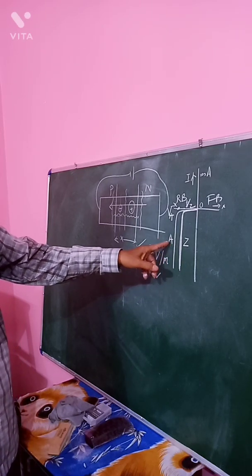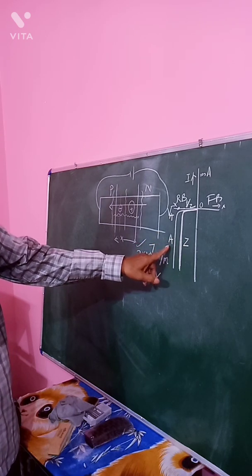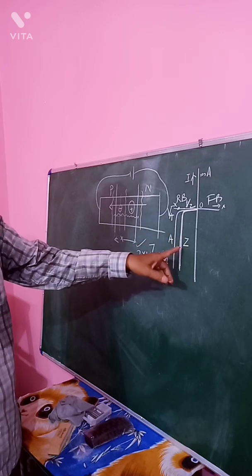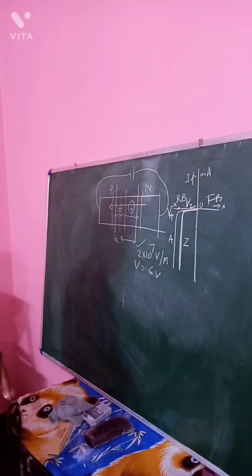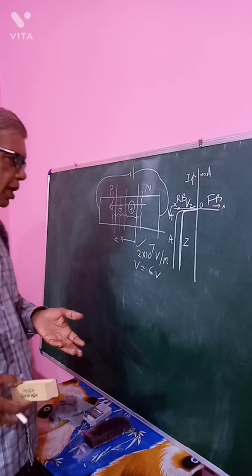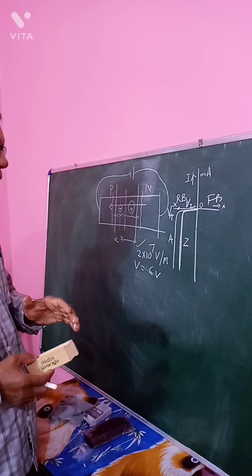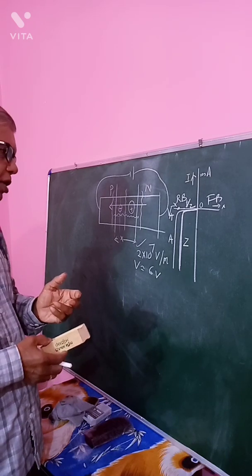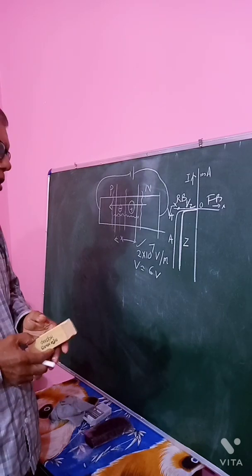Now, avalanche takes place because of collisions of electrons, Zener because of the rupture of covalent bonds due to high or intense electric field across the junction. Whether it is avalanche breakdown or Zener breakdown, the current increases so sharply that unless we control the amount of current passing through the junction, there will be thermal breakdown or thermal runaway of the device.